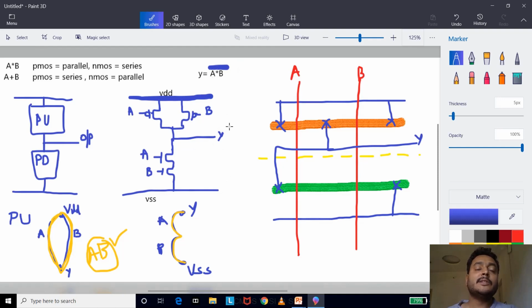So you should remember, this is a CMOS circuit. CMOS means complementary metal oxide semiconductor, right? Whatever circuit you design using PMOS and NMOS, the result will always be the complement of the input combinations. That's why an inverter, with one PMOS and one NMOS and one input A, gives A bar. Similarly, the arrangement you make here using your transistors gives the complement of that particular structure. So if we design A star B, you get A B whole bar. That means this is your NAND circuit.